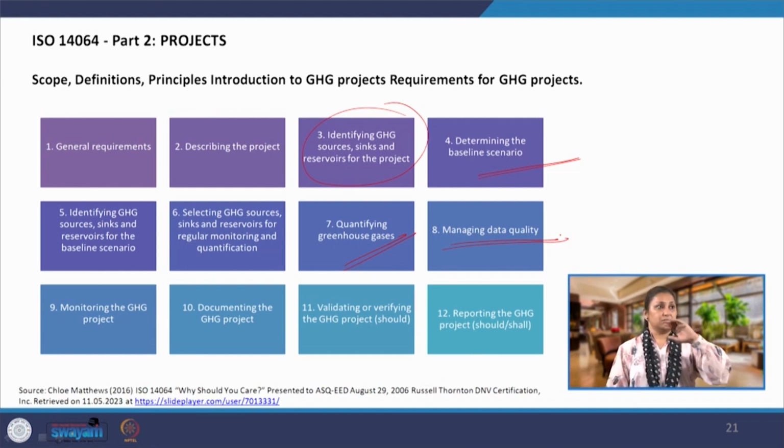For example, HVAC conditioning, a lot of energy goes into conditioning. We have to know specifically how much is going in artificial lighting of the place, and how much is going in the air conditioning. If I know that artificial lighting is consuming a lot of energy, maybe I will specifically look at the design issues or the change of material to bring in some daylight and reduce my consumption of energy for artificial lighting.